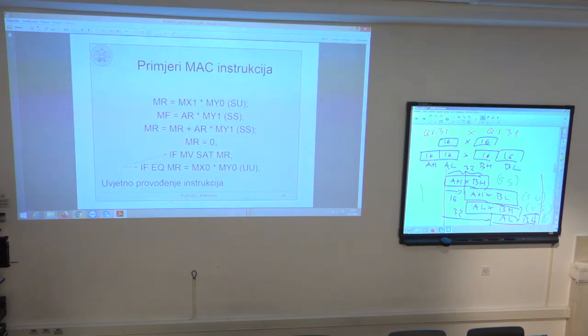I have example here. Do I have example? No, I don't have example here. So instead of having this flag, signed, unsigned, I put RND in the brackets, and that means round. So multiply with rounding. In this case, I cannot specify signed or unsigned. It automatically implies signed times signed. So this round automatically implies that both arguments are signed, and it means that after multiplication, I want to do the rounding. What does it mean?